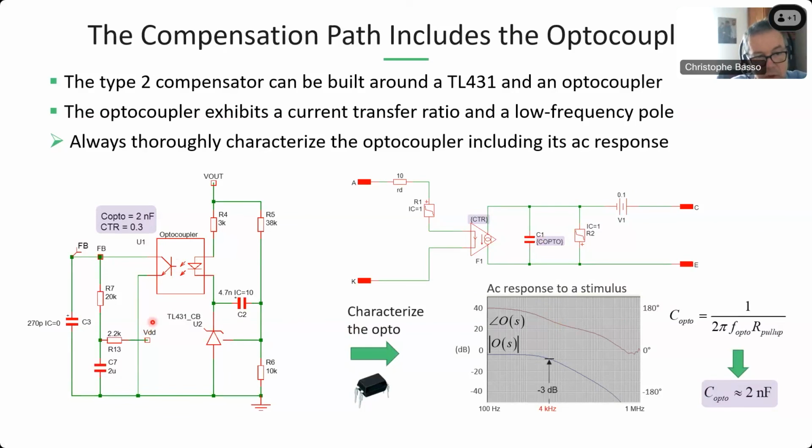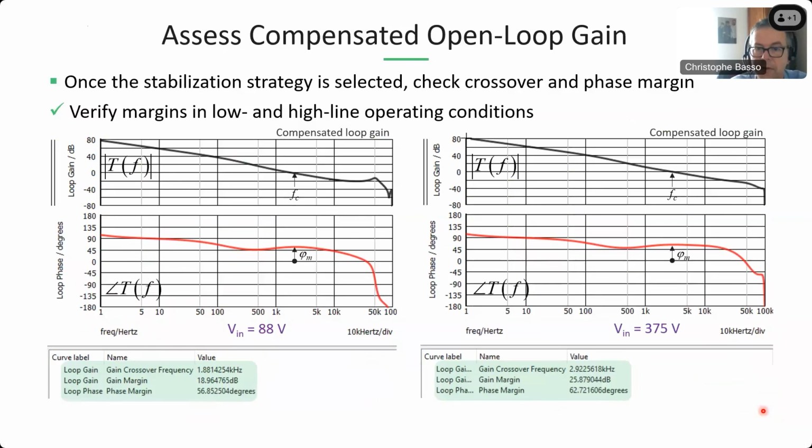And here, this guy is going to apply an extra parasitic capacitance in addition to the one you will place at the feedback input. So it's important to know, in the particular case where the pull-up was probably something like 20 kilo ohms here, that the parasitic capacitance is about 2 nanofarad, which is quite high.